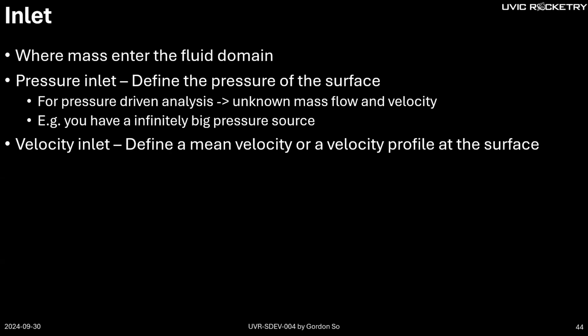Velocity inlet is when you know a velocity or a velocity profile. Remember, when we say fluid velocity, a lot of times we're just mentioning average velocity, because the actual velocity of a flow, let's say in a pipe, will look like this, a fully developed flow. When we say mean velocity, we're just taking the average, but the velocity is actually different at every point on the surface.